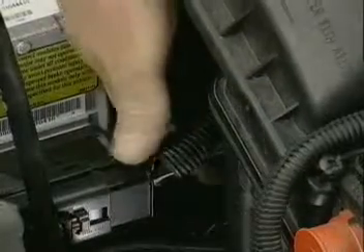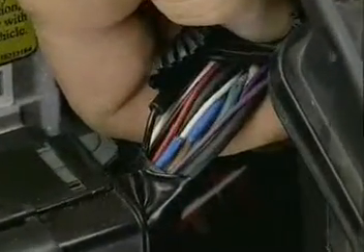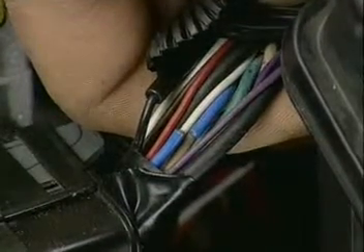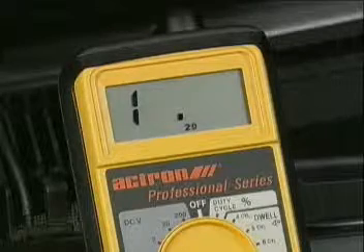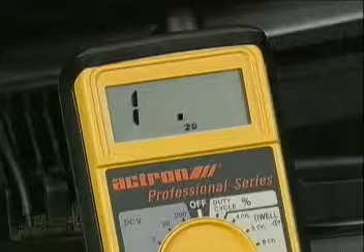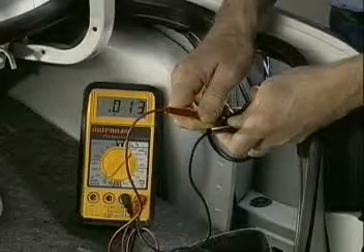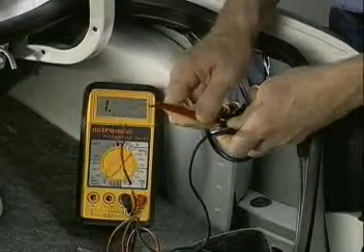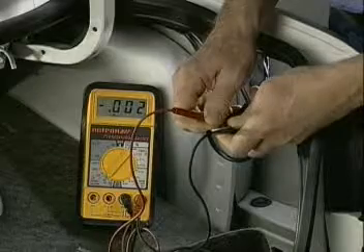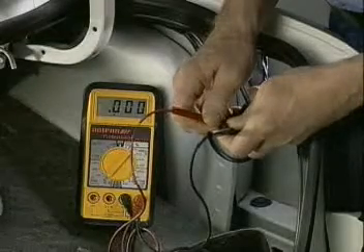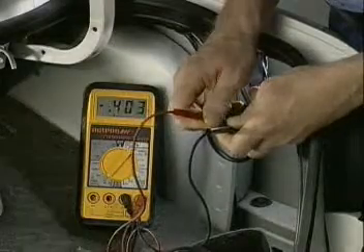Open circuits have a break in a wire or open wires in a sensor. Open circuits can be detected with a digital multimeter using the ohm meter function. Open circuits will have infinite resistance, as current cannot flow across a break in the circuit. Shorted circuits mean that the current in a circuit is finding an alternate path to ground. Shorted circuits will have continuity to ground when tested with a digital multimeter using the ohm meter function.